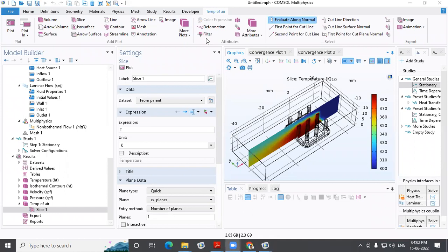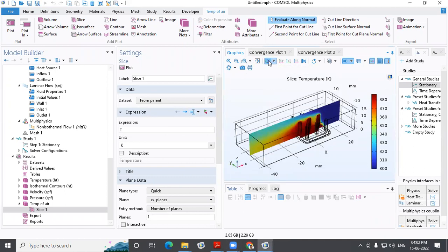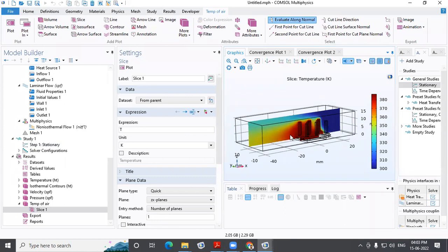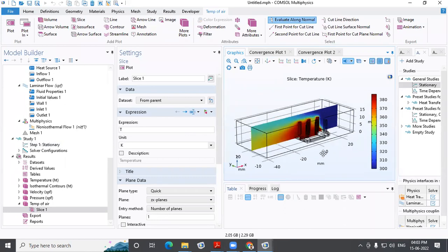Waiting for the simulation. Okay, so Gulam sir, let me know what results you are getting. Now, what should be the criteria? You can do a parametric analysis with this also. You can change the inlet air temperature. You can change the heat rate here and check the cooling in this case. How to measure the cooling?